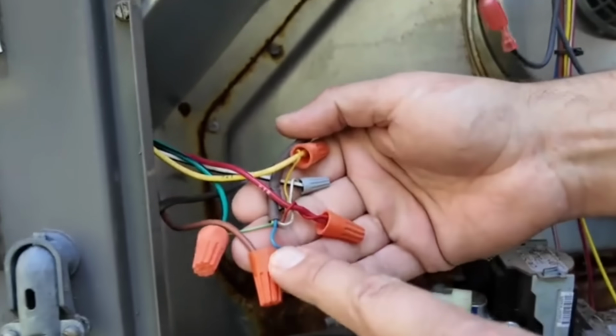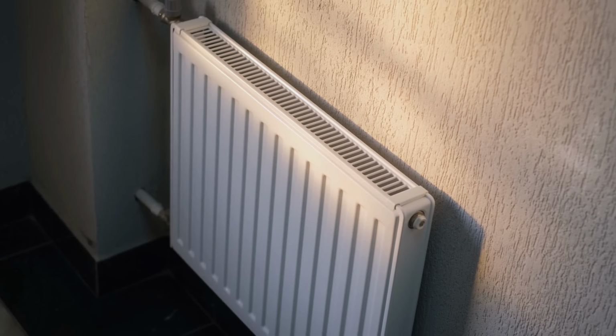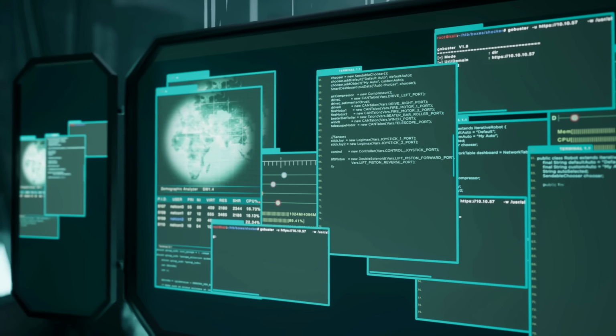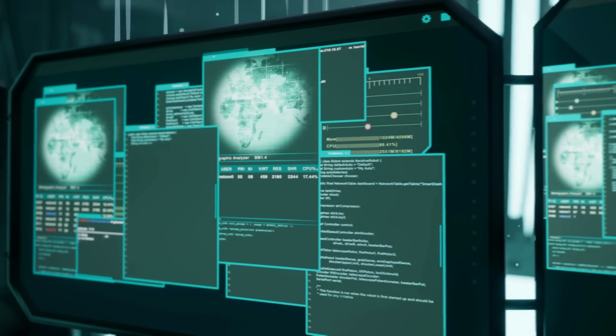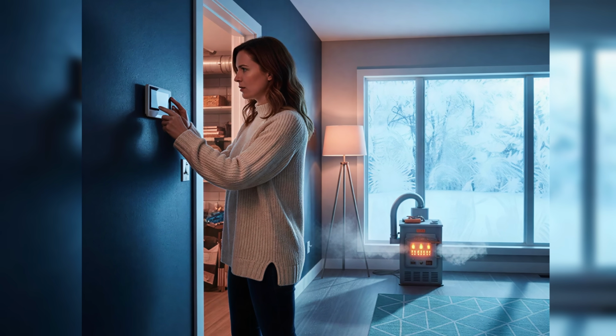In the old days, thermostats had a literal sliding wire called an anticipator that used electrical resistance to guess when the room would be warm. Modern digital units use an algorithm to do the same thing, but if your contractor didn't calibrate it for the specific length of your ductwork, your furnace is shutting off before the heat actually reaches the furthest bedroom.